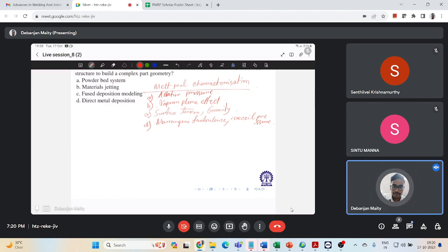In conduction mode, you are locally melting the material to form a molten pool, and it is characterized by a shallow and wide pool, mitigating defects. However, if the energy density is high enough, the keyhole mode can occur and form a deep, narrow pool where the metal evaporates, generating some recoil pressure and a capillary which is called a keyhole.